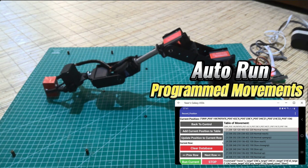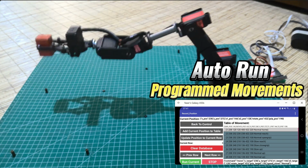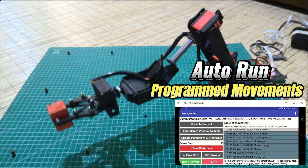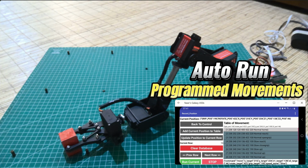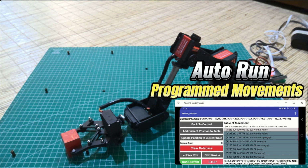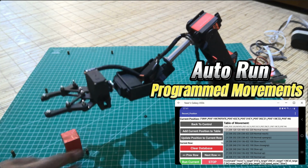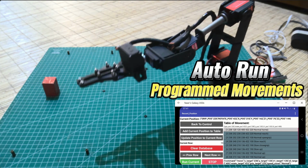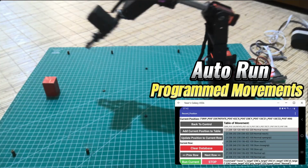Now the robot is moving according to the steps in the database, starting from the first step. During the robot's movement, there are slight jerks. Perhaps we need to adjust the delay values to make the movement smoother and not too fast. After reaching the last step, the robot will return to the first step, and this cycle will continue until the stop button is pressed. Upon pressing the stop button, the robot will cease its movement.